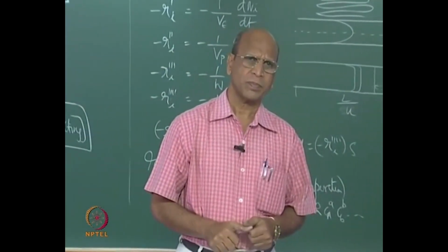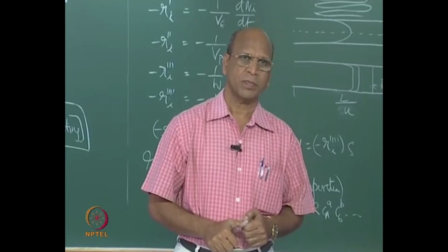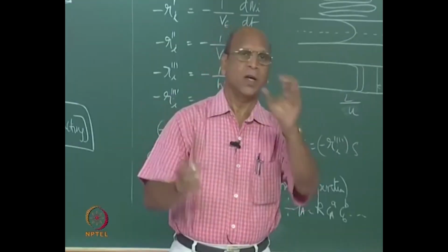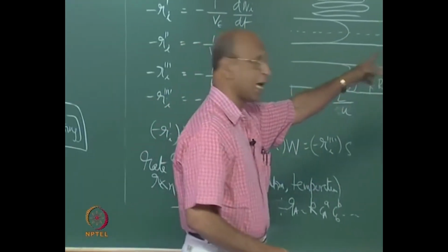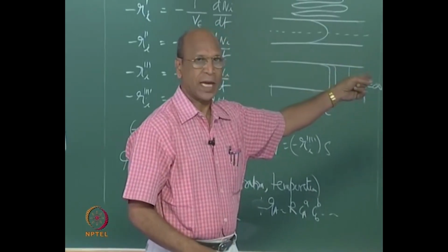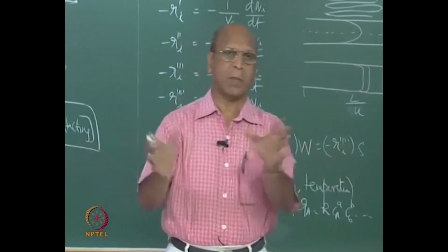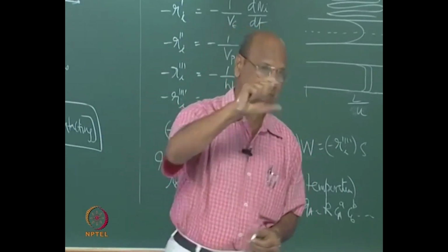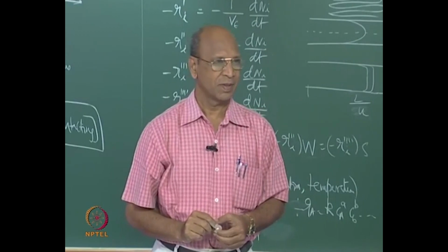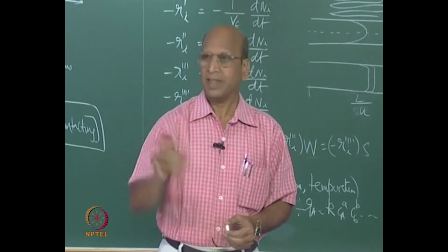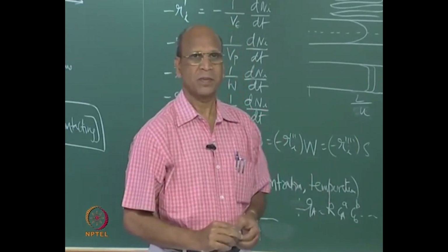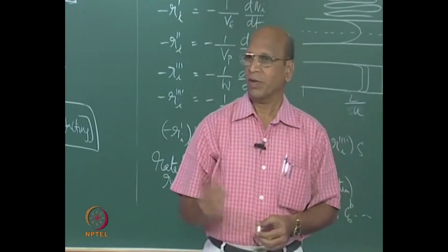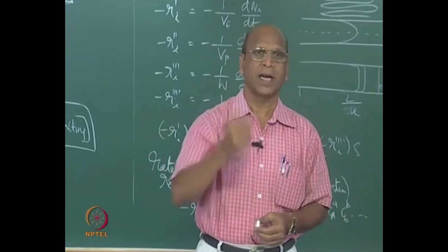CSTR tank volume is also very big in comparison. If we use plug flow, then we can use multiple. Yeah, but there the diameter is fixed most of the time. You cannot go to so big a diameter in plug flow. Okay, what is the diameter you can guess in any plug flow reactor? Diameter. Max, in terms of centimeters or inches. 5 centimeters, 15 centimeters. Yeah.